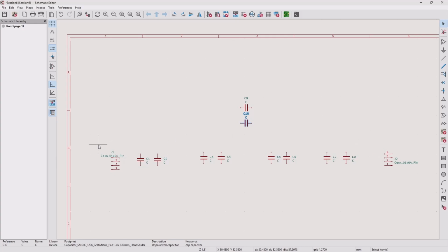What I'm going to do is move this connector up, because we're going to use pin 3 for our source, and pins 1, 2, and 4 are going to be used as a ground. And the only reason I'm using a 4-pin socket is I want some stability on that board, because you're going to be pushing it in and out of either a connector or the breadboard. So it's probably better to have a little bit of stability with it.